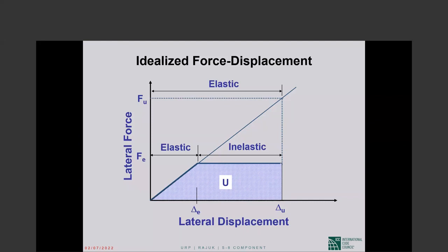Seismic design is always a two-part affair. Design for the forces that we have chosen to design for, the strength level, and detailing for the inelastic deformation capacity that we must have in order to be able to design for the force level that we have chosen.